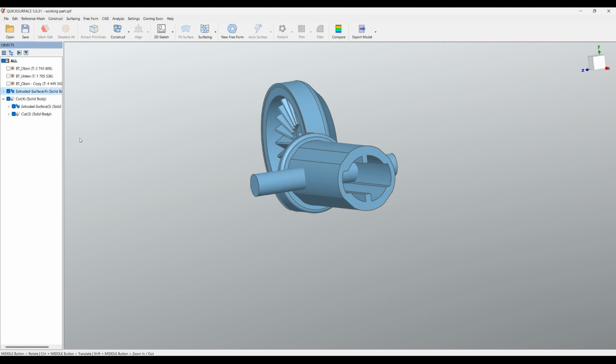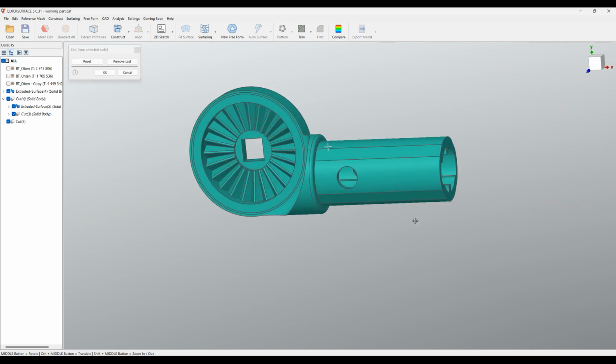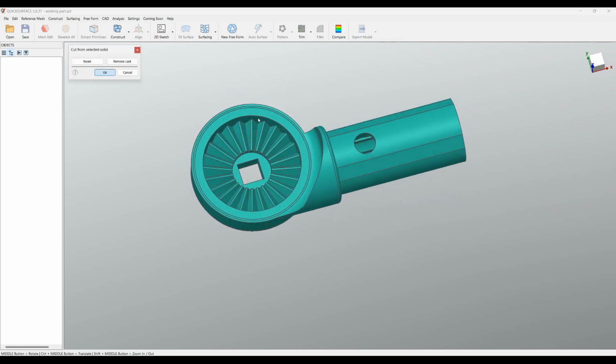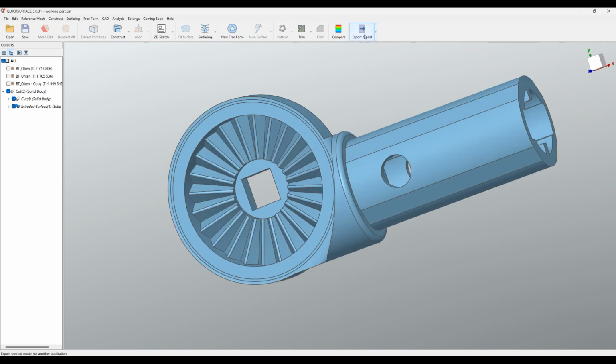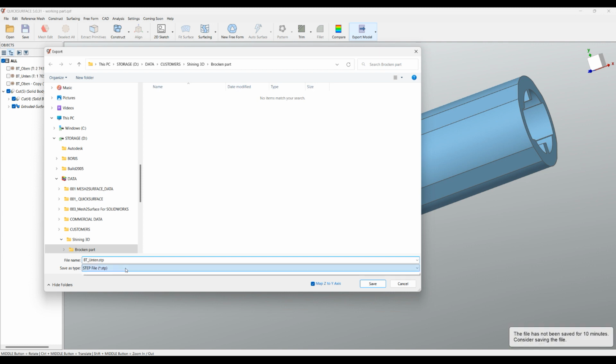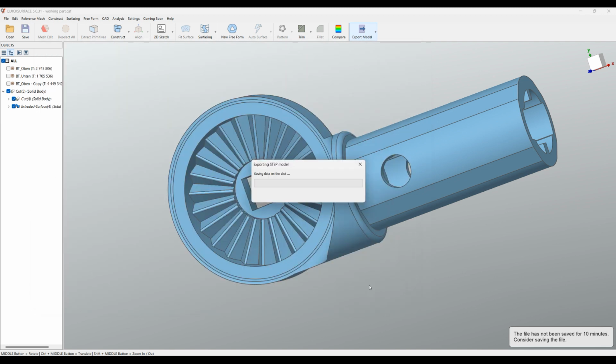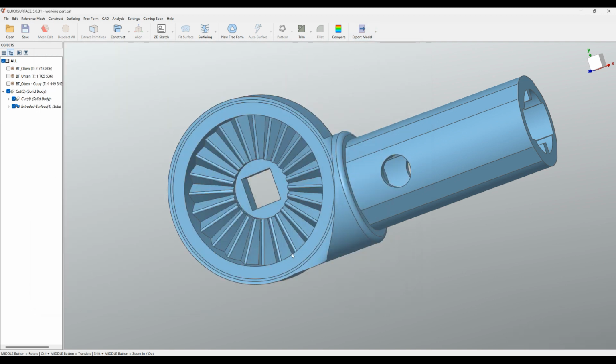One last step that we need to do is from our main body just to drill a hole by selecting this extrusion. And our project is completed, and this part can be exported as a step file. You can either map the Z to Y or not, just normally I leave it as it is, and you can send this to the printer for printing.